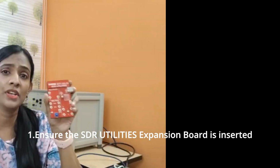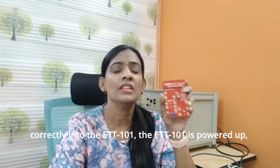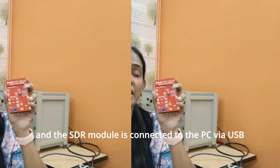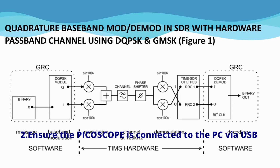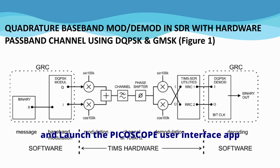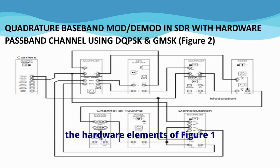Ensure that the SDR utility expansion board is inserted correctly into the ETT 101. The ETT 101 is powered up and the SDR module is connected to the PC via USB. Ensure the PicoScope is connected to the PC via USB and launch the PicoScope user interface app. Patch the arrangement in Figure 2 to implement the hardware elements of Figure 1.